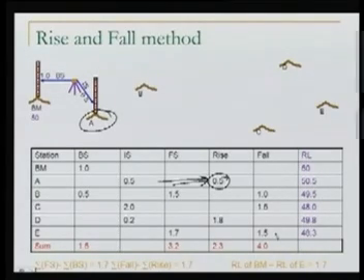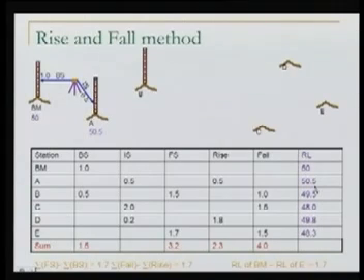Well, next I know the RL of benchmark, and I know that A is rising up from benchmark by 0.5, so I can compute the RL of A also, which will be 50 plus 0.5, so this is 50.5. Well, having done that, next what we will do, because we want to determine the RL of B, we will again take a foresight as we have done earlier also, and the foresight in this case is 1.5.